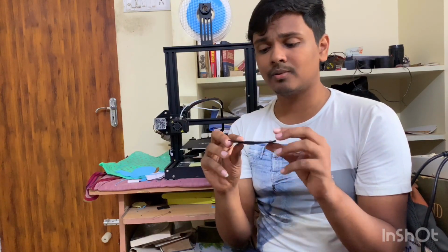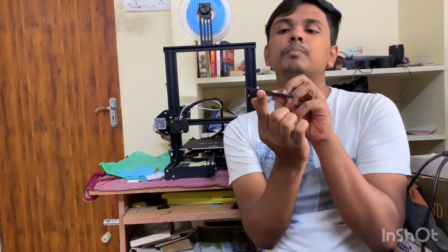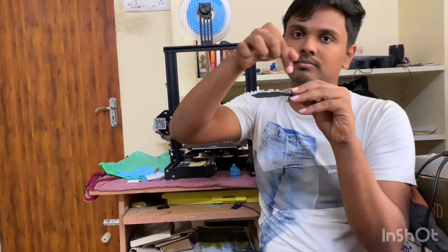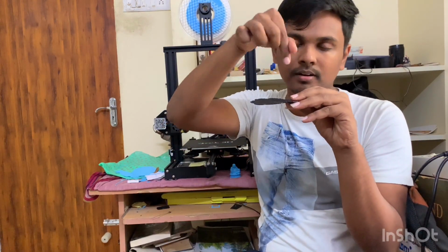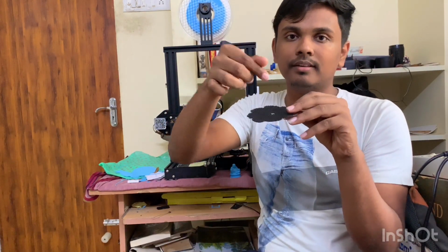What happens is that when you are printing, if this layer is not good, it just starts to peel off like this. And if it is heated too much, it just peels off. And if the 3D printer is going to print above the surface which you have designed, this just peels off and it spoils the whole model and wastes your whole material. So yeah, now let's concentrate on raft settings.